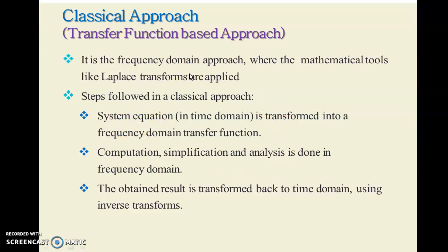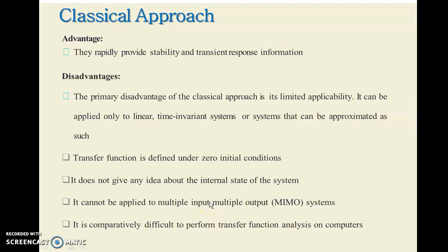The classical approach is basically a frequency domain approach where mathematical tools like the Laplace transform or any other transform are applied. So a given system is transformed into a frequency domain transfer function. Computation and analysis is done in the frequency domain itself, and finally the obtained result is converted back to the time domain using inverse transforms.